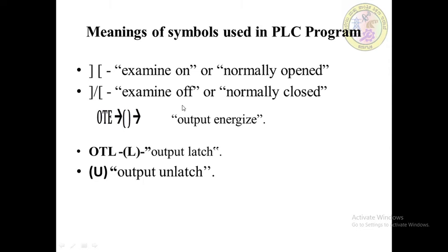If you use the output latch symbol, the bit must be reset, otherwise it will remain on even if the rung condition goes false. Output latch is like output energize, except that once the bit is set with OTL, it is latched on. For output unlatch, the address of the bit must be the same as the latched one.